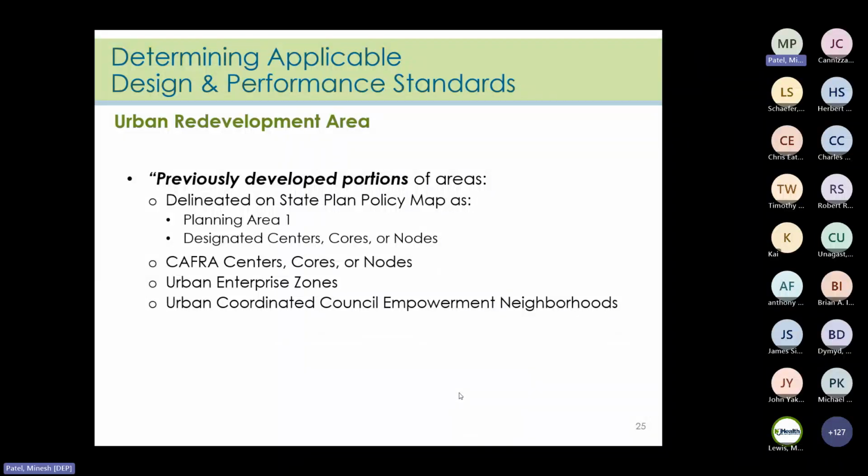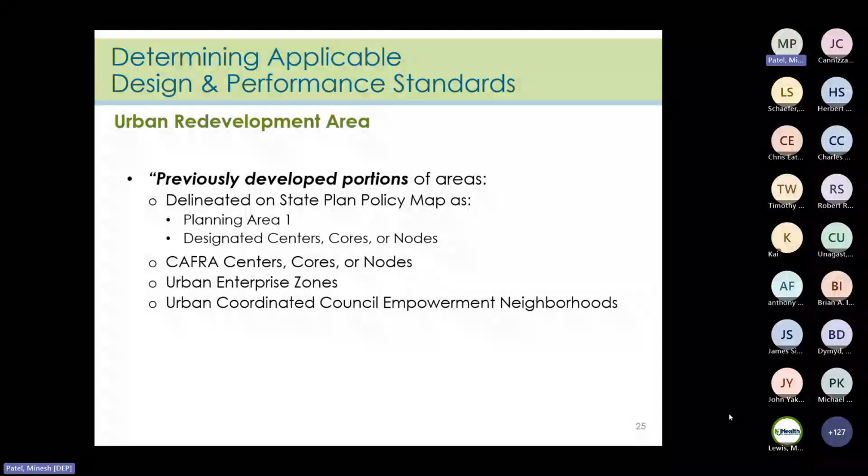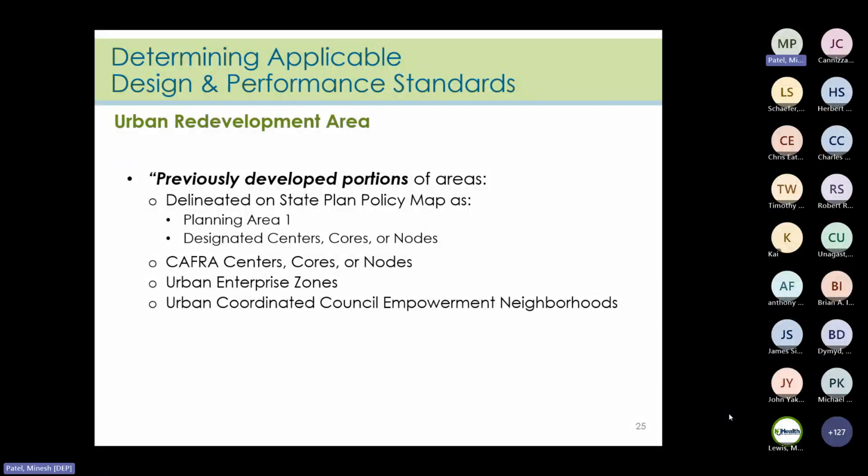If the reviewer finds that woody vegetation has returned to areas of a previously developed site, this exemption is not going to be allowed. Removing woody vegetation and putting new construction over this portion of the site will result in a loss of groundwater recharge. So that is why. The reviewer can check the NJGeoWeb to determine whether the rest of this information is applicable to the site.